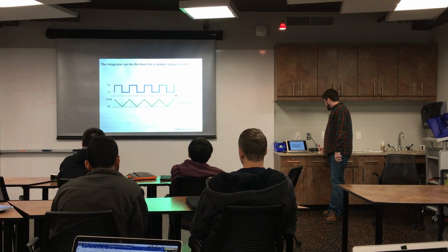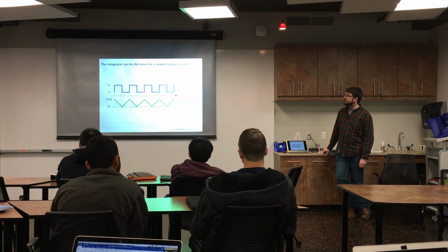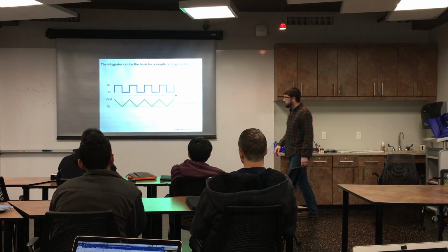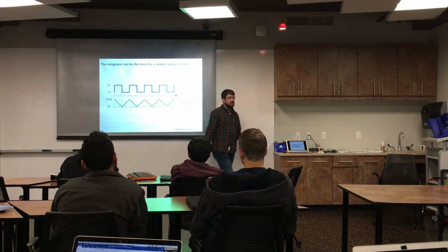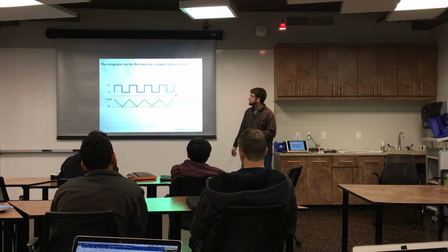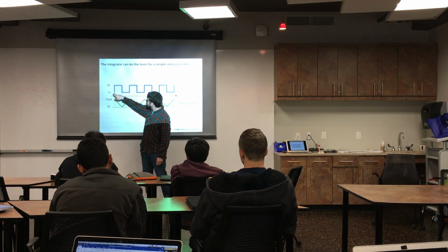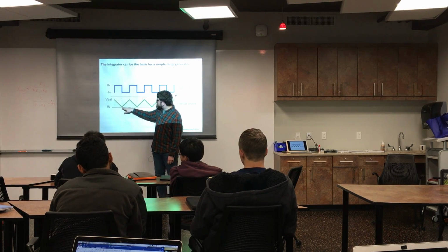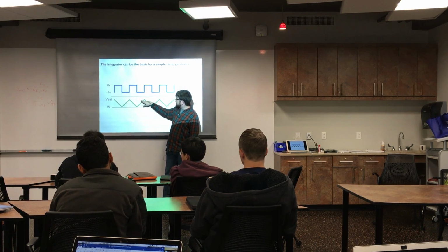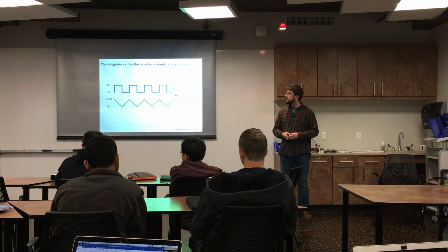One of the nice signals in electronics is a ramp generator. We actually use them in the lab for several things. You can create these nice sawtooth looking waves. One way to do that is to use an integrator and feed it a square wave, right? So we're at 0 here, so we're going to be going down. We go to -1 volt, we go up, and we have these nice ramps or sawtooth patterns. Right?